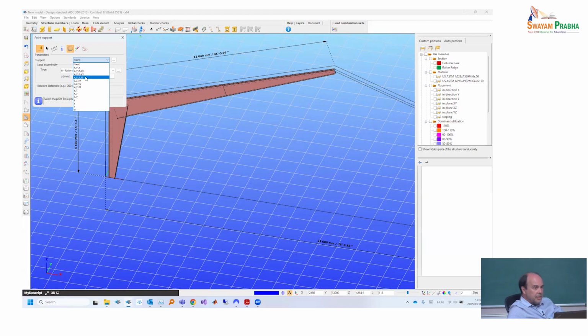That means restrained displacement in all three directions, which are considered as global directions because this symbol is selected. As I said also yesterday, we could have user-defined and local, but we stay with the global, which is the default. X, Y, Z, and ZZ means rotation around the global vertical Z direction. So X, Y, Z, ZZ will be fine for us.